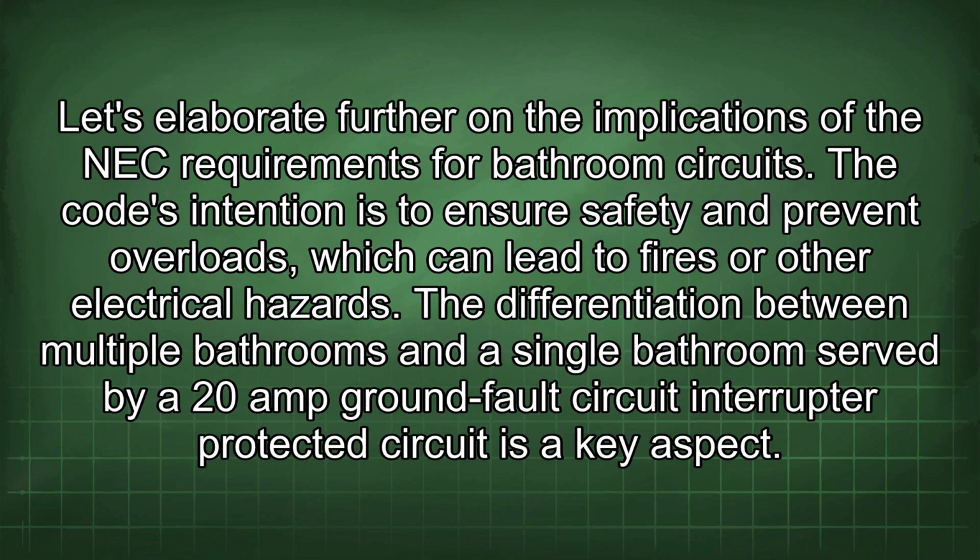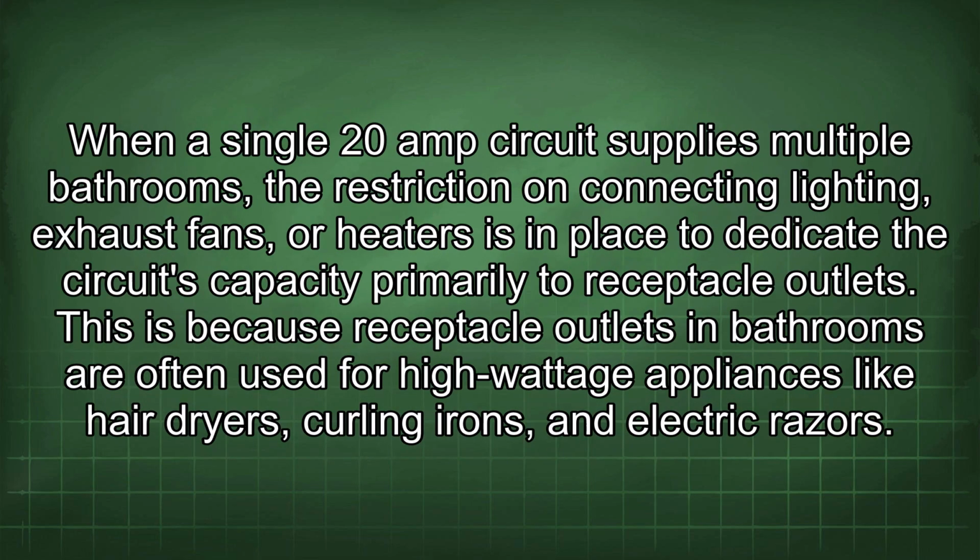Let's elaborate further on the implications of the NEC requirements for bathroom circuits. The code's intention is to ensure safety and prevent overloads, which can lead to fires or other electrical hazards. The differentiation between multiple bathrooms and a single bathroom served by a 20 amp ground fault circuit interrupter protected circuit is a key aspect. When a single 20 amp circuit supplies multiple bathrooms, the restriction on connecting lighting, exhaust fans, or heaters is in place to dedicate the circuit's capacity primarily to receptacle outlets.